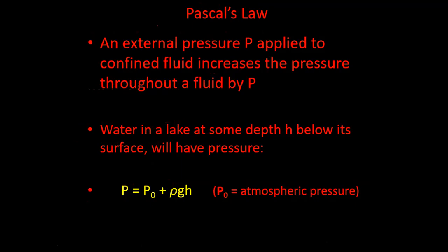And this is what's referred to as Pascal's law. Any external pressure that's applied to a confined fluid increases the pressure throughout the fluid by some value of P. So if we go to the bottom of a lake or the ocean, this is what we will get. And we've already seen this result. This is just putting a name to it. P is equal to P0 plus rho gh.